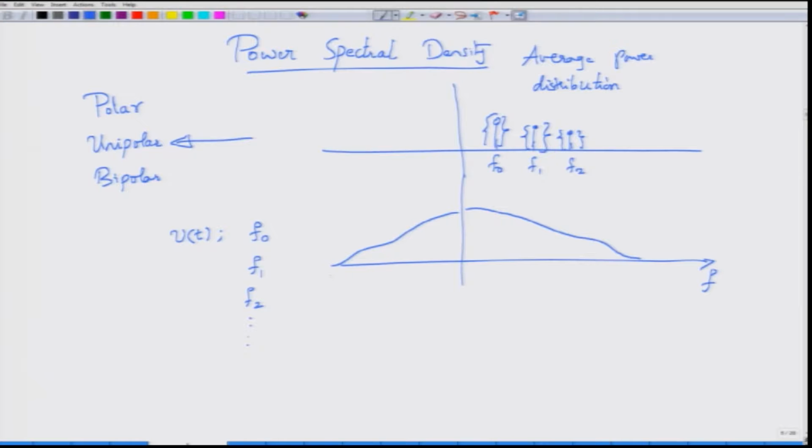So, for example, this is called a two-sided power spectral density, PSD being the short form, and of course power spectral density is a function of frequency f. This is the 0 frequency, and you can see here that the power spectral density is more or less uniform, which is a characteristic of a real autocorrelation. We will not get into that detail here. So, if you want to look at how much power is associated with a band of frequencies centered at f0, this is the band that I am looking at.